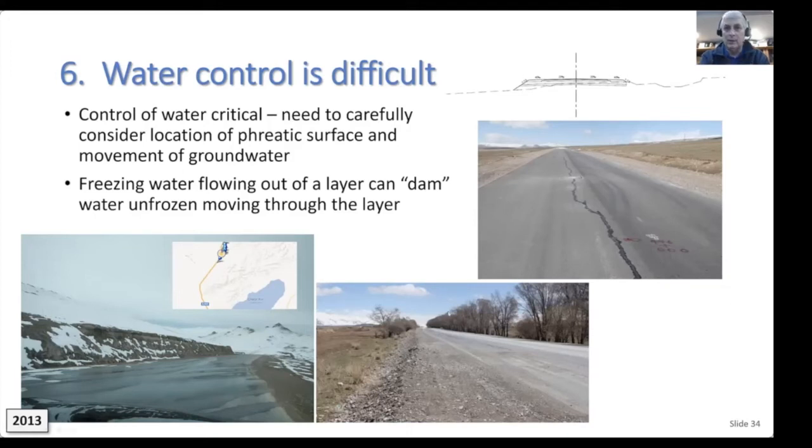We had a roadway like this that water was actually flowing all the way down this road through the subsoil materials and causing thermal or frost cracking in this region here. Even though the sides of the road were adequately drained, as the water flows down, it comes to the sides and then freezes and causes a dam, and then the road cracks. Same situation here. All of this area here was basically damming up and causing a crack. The phreatic surface associated with these slopes, you'll be surprised at how, if you don't have drainage blankets, you can get cracking in these pavement systems.